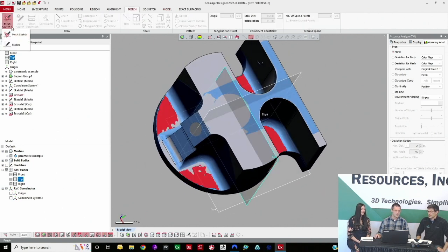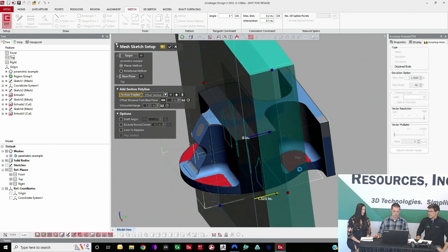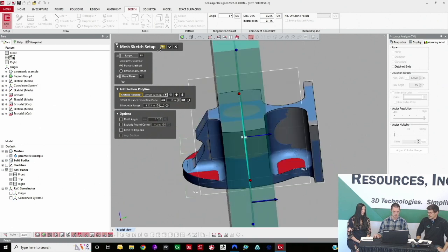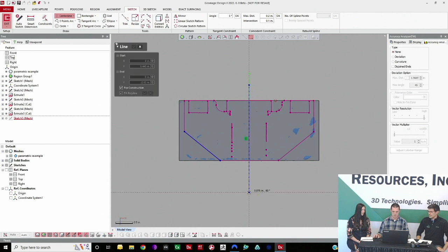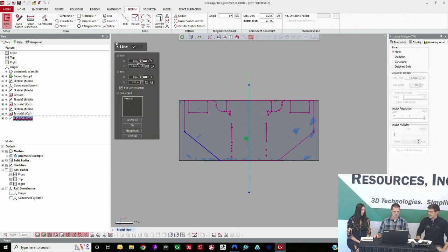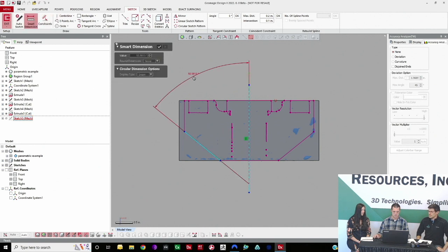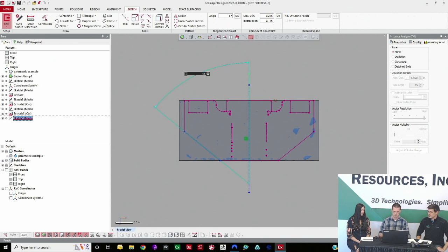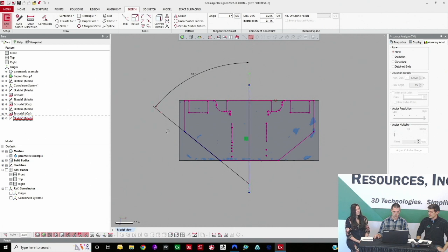So just now finishing up the overall outer shape, and then I'll show you some pretty cool wizard tools using fillets and things like that that are helpful for estimating fillet sizes. Go ahead and drop this guy in here. I'll also constrain his angle. Make sure this is on 0. Yep. Mirror him over.